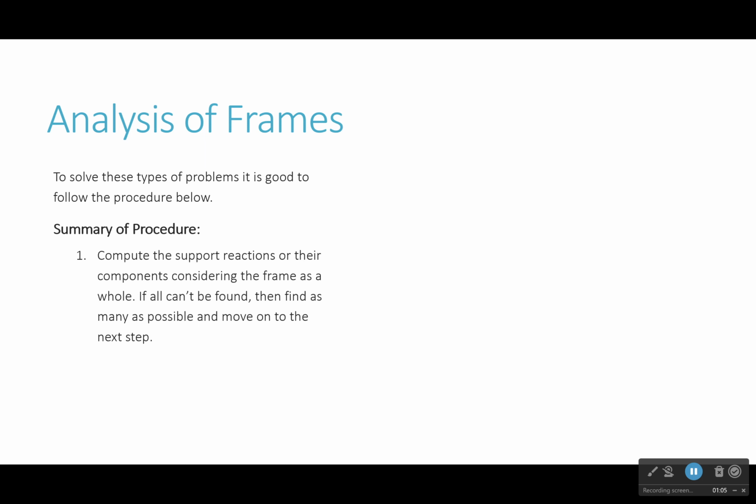Okay, so first, like always, support reactions. Get rid of those pins, get rid of those rollers, turn them into support forces. Do what you can and see if you can solve them all. If you can't solve them all, then get as many as you can and continue to the next step.